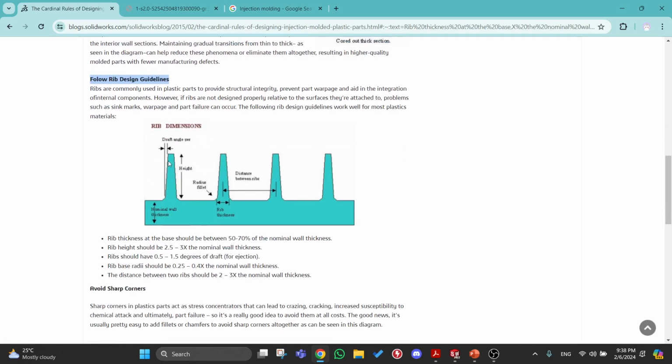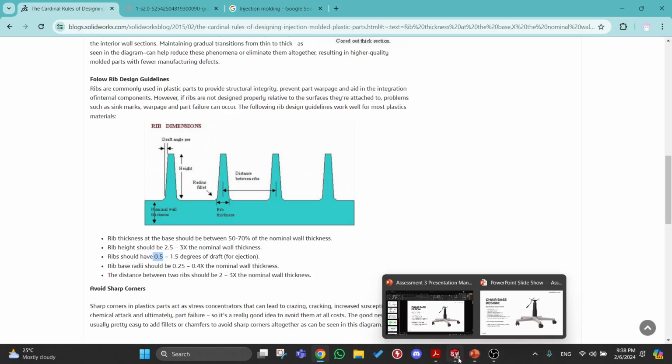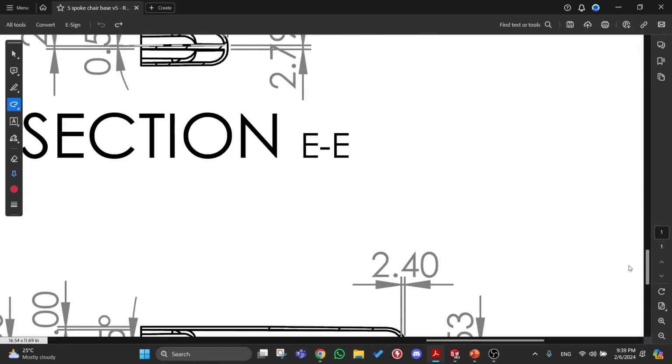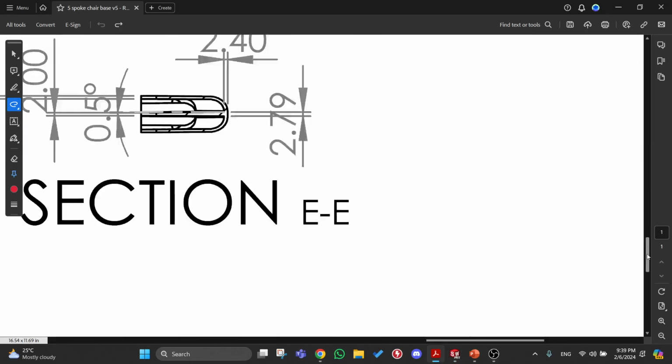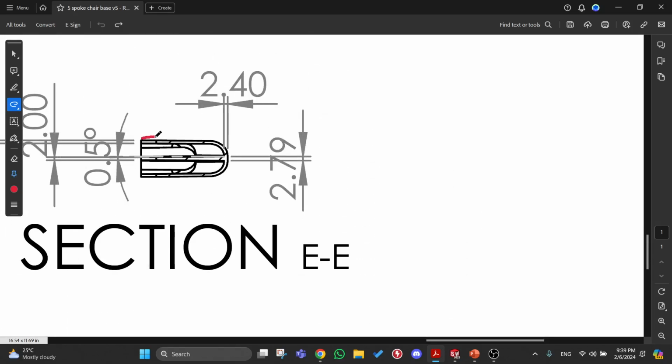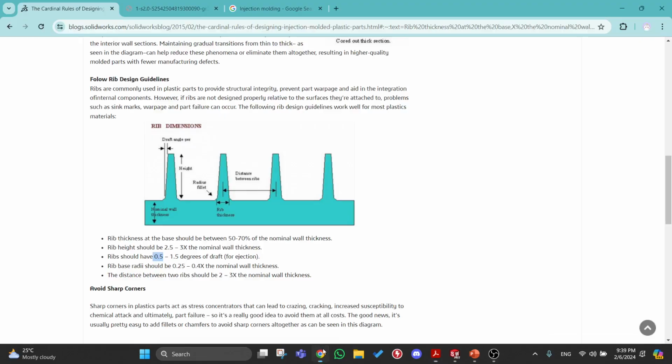That's why for it to come off smoothly as an injection molded part, you can see here the Protolabs design guidelines. You need to have at least 0.5 to 1.5 degrees, or a minimum of 0.5 degrees of draft. Let me just show you here, and hopefully you are able to understand this. You can see there's a slight draft, a 0.5 draft around here. All of this here to here is 0.5 degrees. That is the minimum. Usually when we are doing manufacturing, we go for 1 just to be safe, because sometimes you have texture, sometimes you don't. This is for smooth surface injection molding, 0.5.